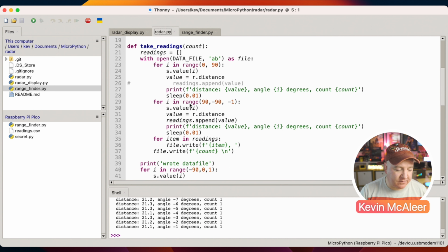So the way that these servos work is they have a center position, the middle position. Say that's straight up, and then you can go -90 or +90 for the whole 180 degrees. You don't start at 0 and go all the way to 180, so I just need to factor that in when I'm doing my code on here. So then we go all the way between 90 and -90, stepping -1 at a time.